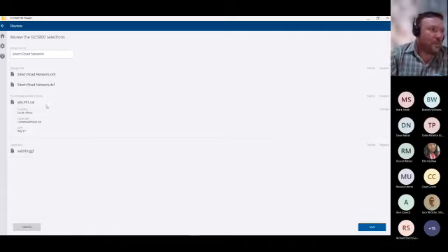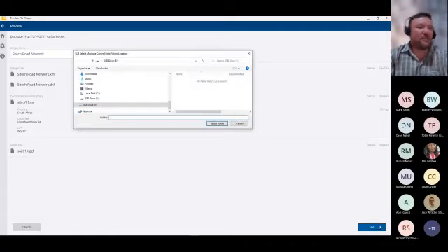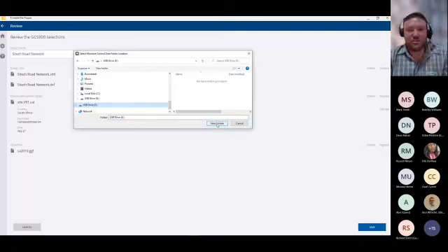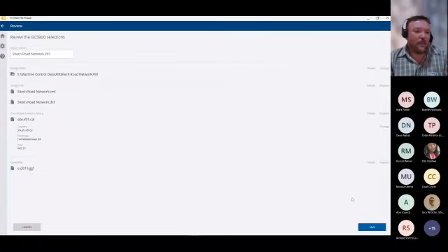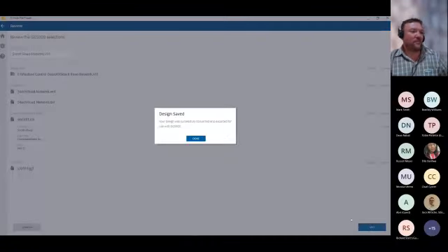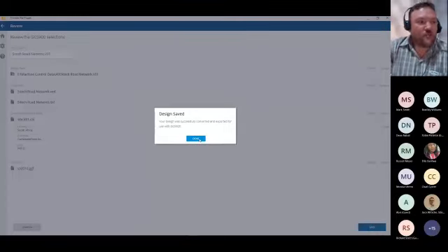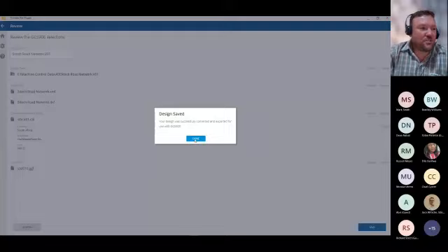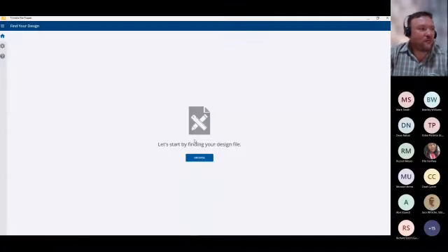If you're happy with this, you just press save, and then it will ask you where you want to write it to. I'm going to write it to my USB device because I want to send it to the machine. I'm going to go to the machine and import it there. So I'm going to select my USB device, select folder, and just save it. And it tells you the design was successfully converted and exported to use with GCS 900. So you're done. This is done for GCS.